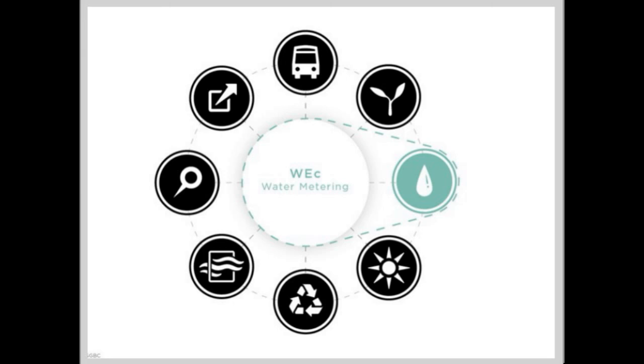The same applies for outdoor water use. Subsystem meters to measure cooling tower or evaporative condenser makeup water can assist in water management and can help optimize cycles of concentration. There are sustainable sites credits such as Rainwater Management, Heat Island Effect Reduction, Site Management Plan, all related to water efficiency credits. Rainwater collected and treated for the credit may also contribute to the related water efficiency credit by reducing the potable water demand. The vegetation you choose for your landscape can influence the credits under sites and vice versa.